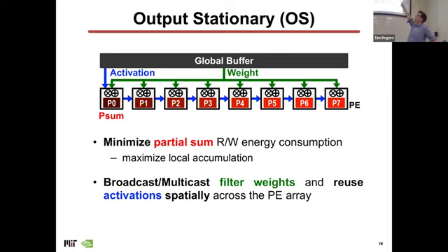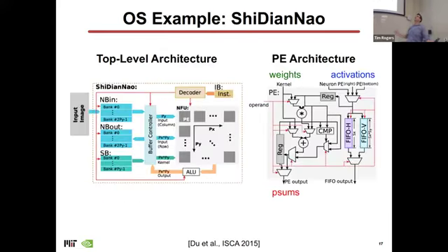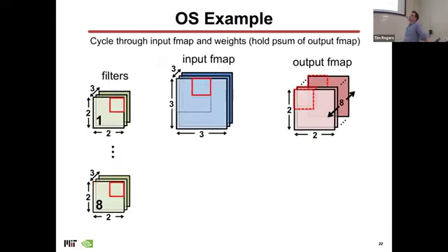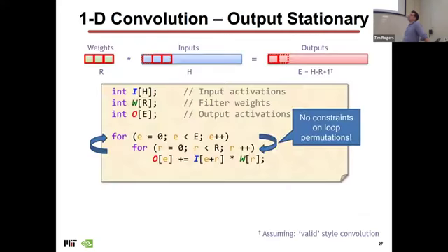It's being fed in from this global buffer, going processing element by processing element, performing the computation. And the weights are smaller, hopefully, so you can broadcast. That broadcast network is less big than the activations, and you are giving each processing element the weights it needs for the activation that it needs at this time. Okay, and orchestrating that computation isn't all that hard, but you need to make sure that it's right.